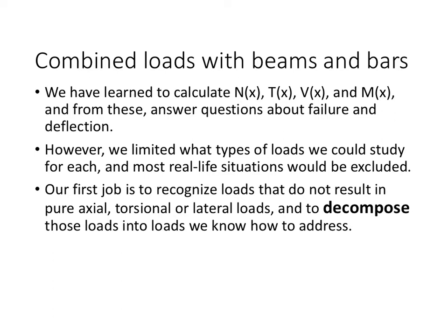So when we consider combined loads with beams and bars, we've learned to calculate these individual types of internal loads: axial, torsional, shear force, and bending moments. And from those, we've answered questions about failure and deflection. However, all of those are limited to these very simple types of loads. And so most real-life situations we could not address with those skills. So what we do now is to recognize loads that do not result in pure axial or torsional loads, and we decompose them into the loads that we know how to address.